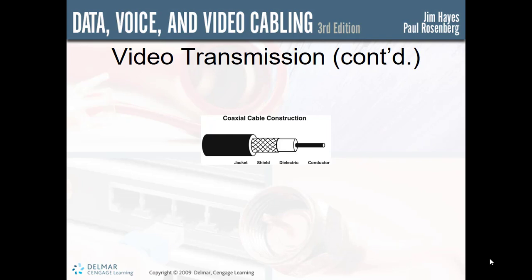One of the very intimidating words used in the TV business is modulation. Now, modulation is simply the function of taking a basic 6 MHz TV signal and modifying it so that it matches one of the standard channel frequencies. For example, the TV signal coming out of the camera at your local station operates at about 6 MHz.